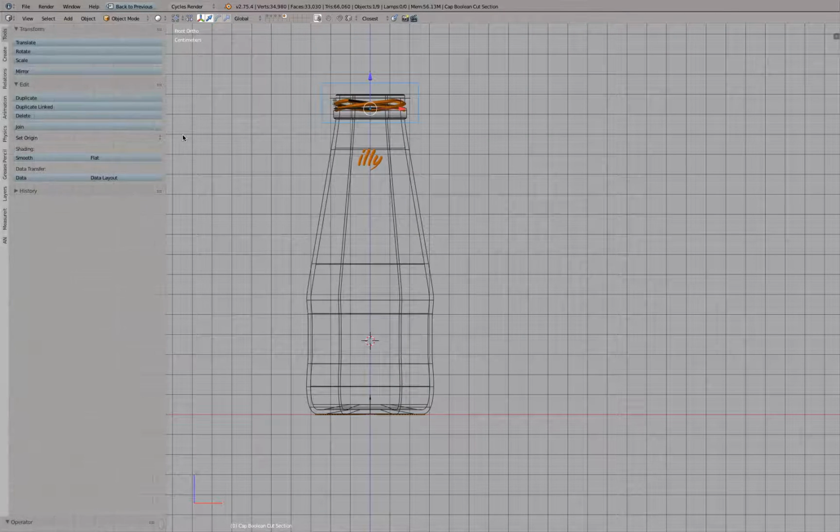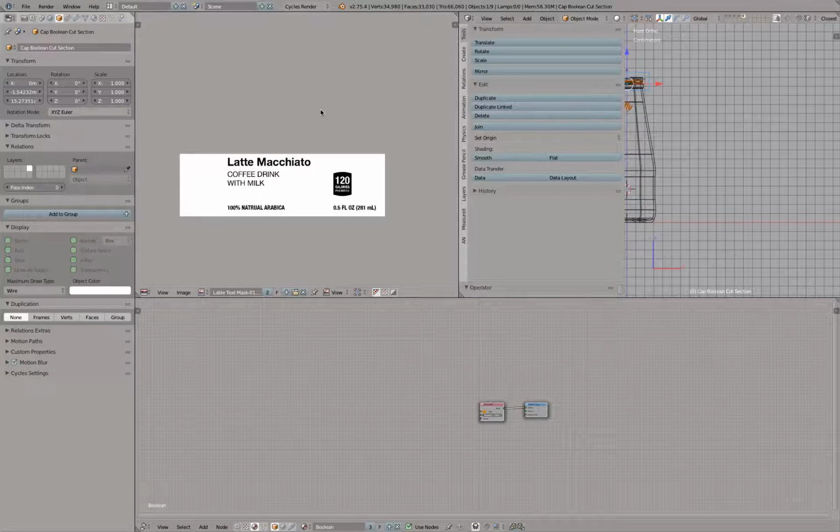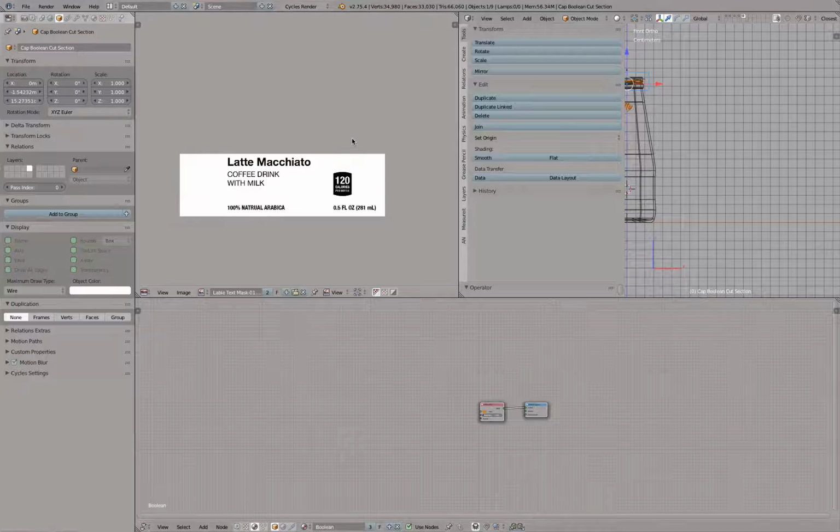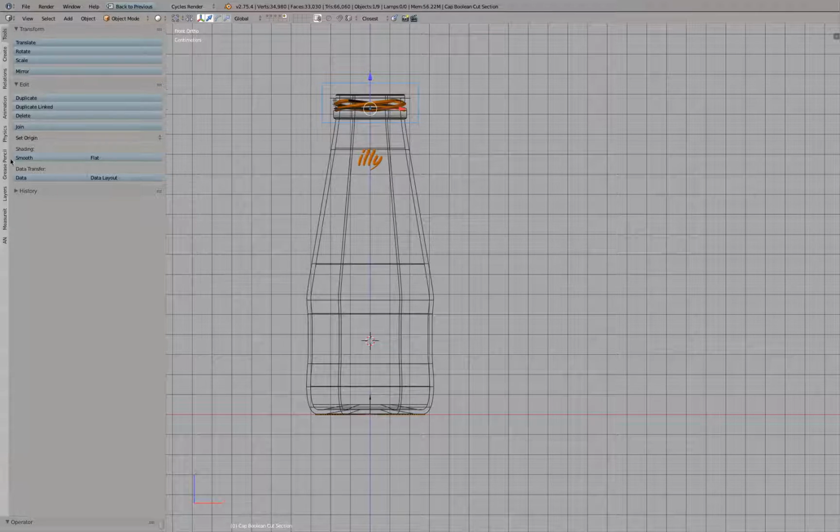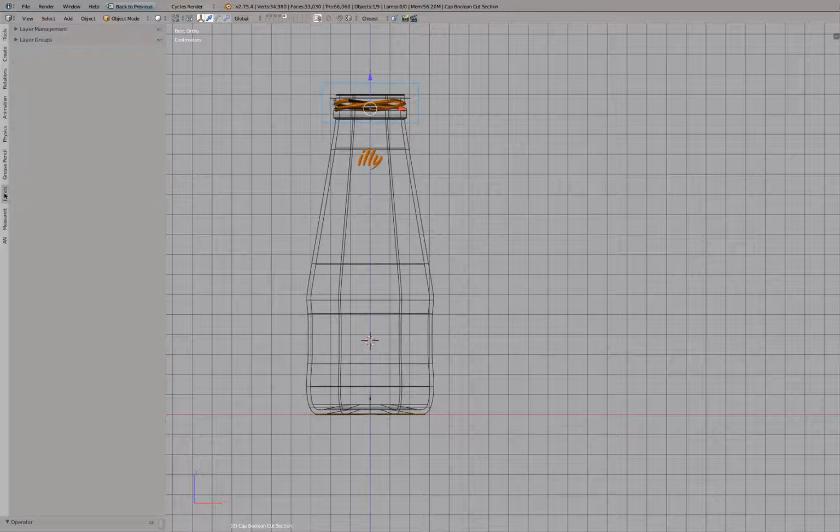So let me go into full screen. By the way, full screen, pretty nice in Blender. Put your mouse over a viewport and then press Shift Spacebar to go in and out. So one command, but by tapping it twice, you make it full screen and go back from the full screen. And inside the 3D view, you now have layers inside the toolbar on the left side.